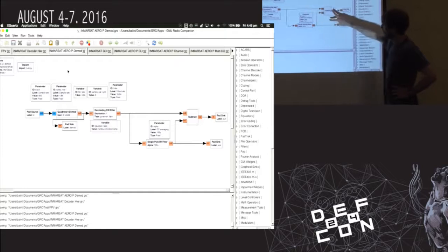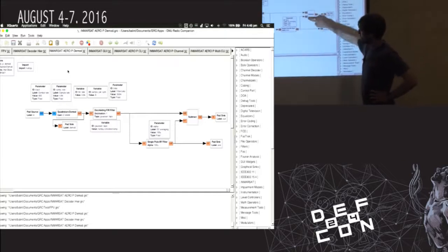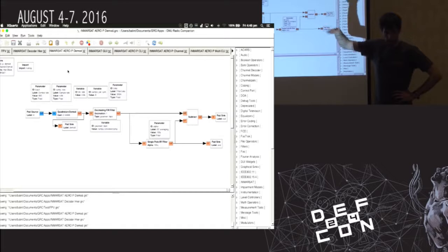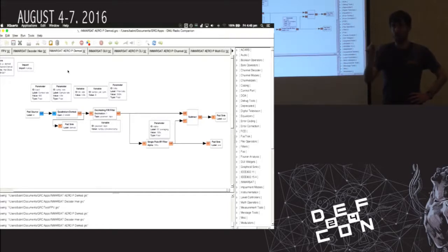And then you can do this very simple subtraction here. So this single pole IIR filter is actually really a long-term averaging filter. And so when you actually see the signal, it'll be moving between two values, hopefully -1 and 1. But it might be elsewhere. But the point is, remember how we were scrambling our incoming signal, which means that the bits are changing between 1 and 0.